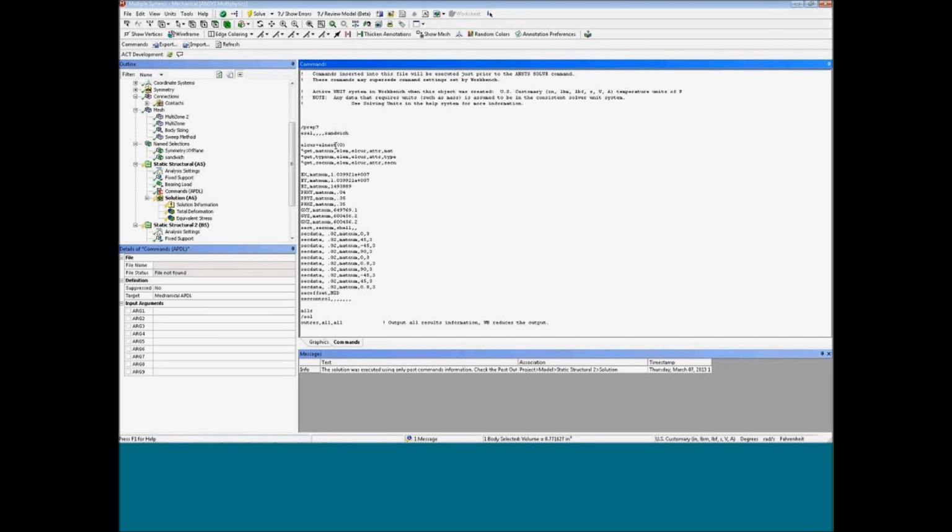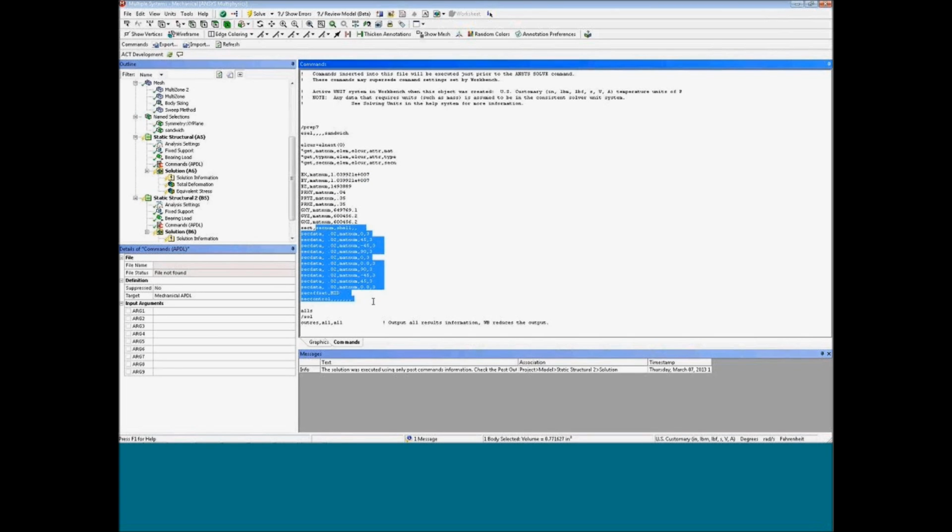So I select those elements, and then I get the material, section and type numbers in here. Pretty much, it does the same thing, a little bit different than that first example of using that parameter, but this does the same thing. So I get that information, and then I overwrite the existing material properties that are in there and put in some composite properties, and then also the section properties for the layup in there. So those are the commands for doing that, and then go back into solution.